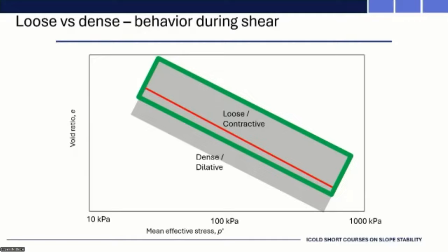And that was about the top 8 or 9 laboratories. So 0.04, here we've got this offset of minus 0.05. So maybe, even though it is probably unintentional, building in that extra conservatism is probably a very good thing, because it's allowing for that inaccuracy of determining the critical state line. Or maybe inaccuracy is the wrong term, but just a variability.